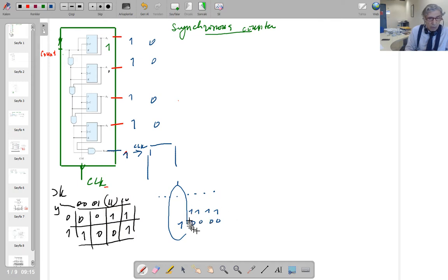Another set of 16 clocks done, then this is going to be increased by 1. So you can extend your counting by an additional integrated circuit, whose clock input is going to come out of this output of the previous counter.